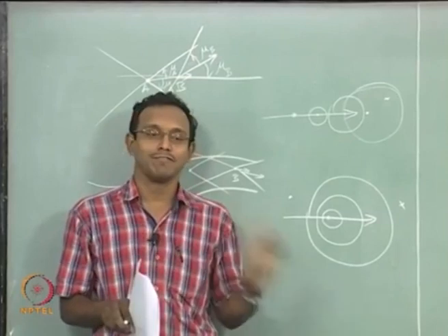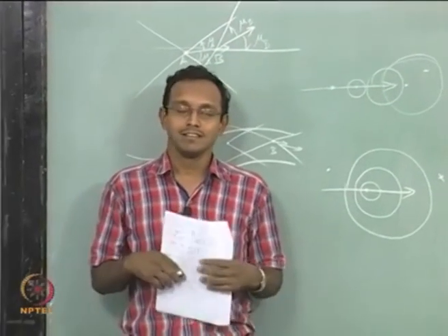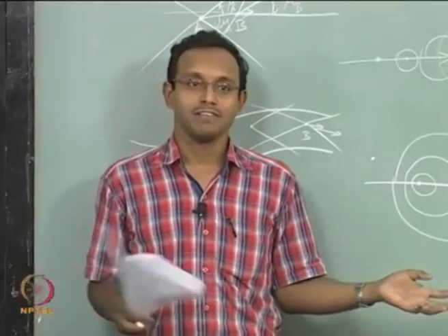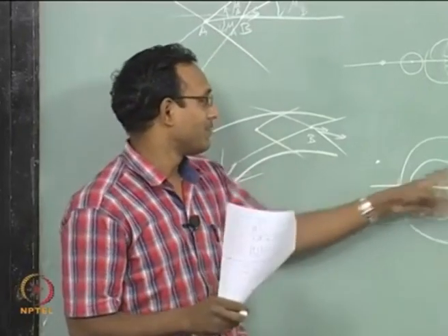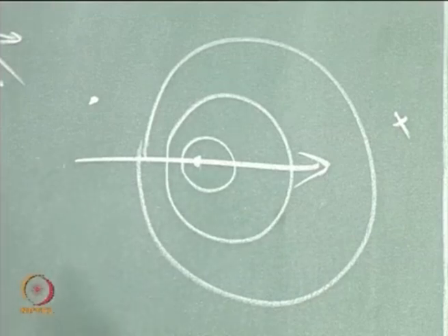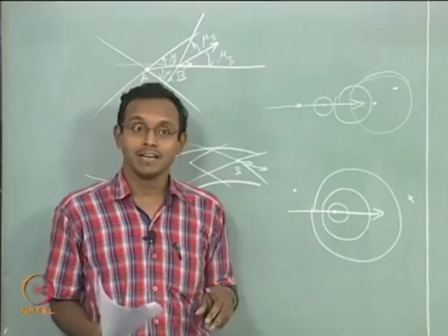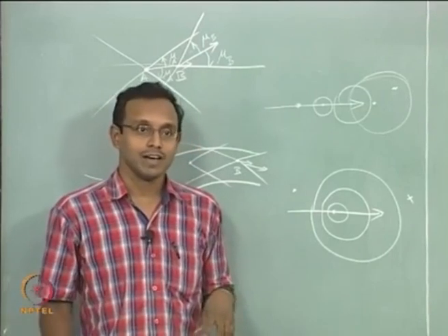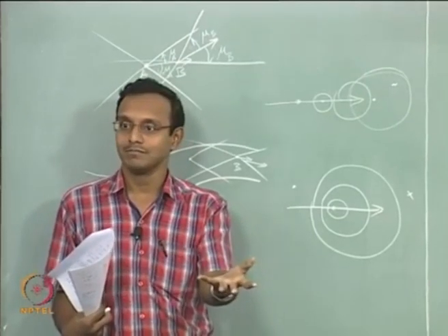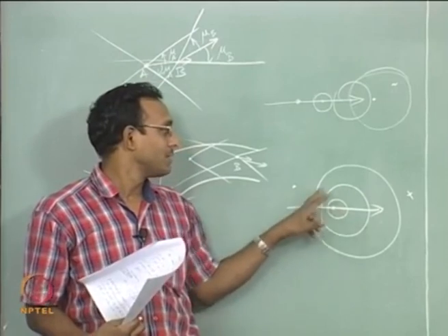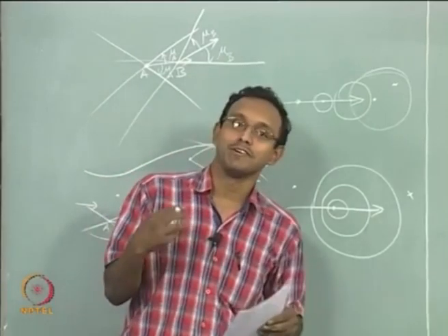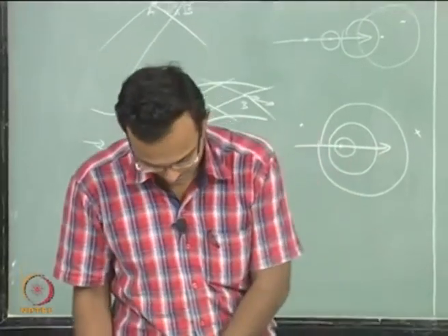When we think about subsonic flows, typically they will say the fluid upstream always knows about what is happening downstream. When they make such a statement, they are assuming they have waited for infinite time, that this wave has already crossed all the points in the flow field which I am looking at. That is an assumption, remember that. In the unsteady world that will not work. I just now created the disturbance, I did not wait long enough, but I want to see what happened to the fluid. So maybe some points will be influenced, but some points will not be influenced. So life is a little more complex when we go unsteady. We will look at more unsteady problems later.